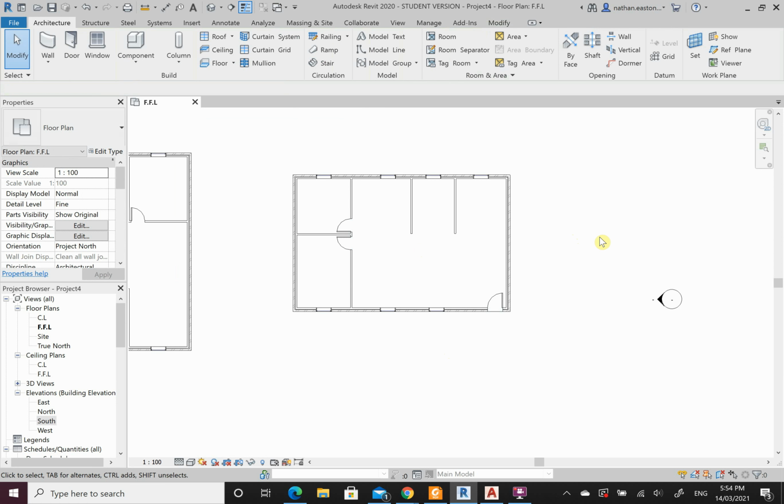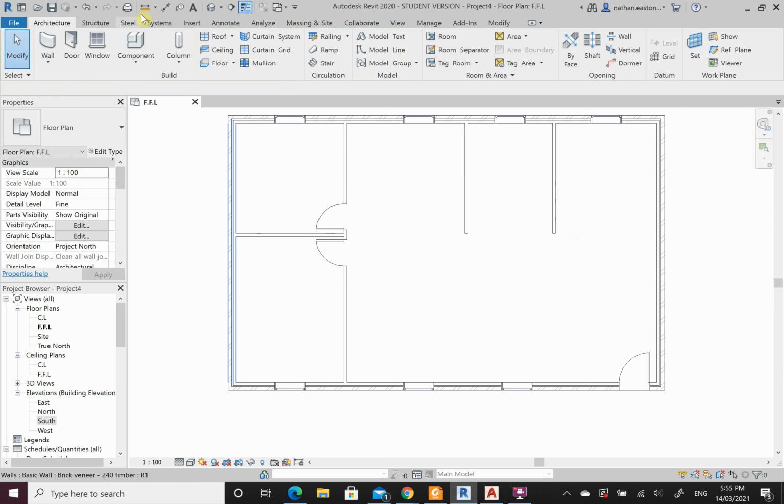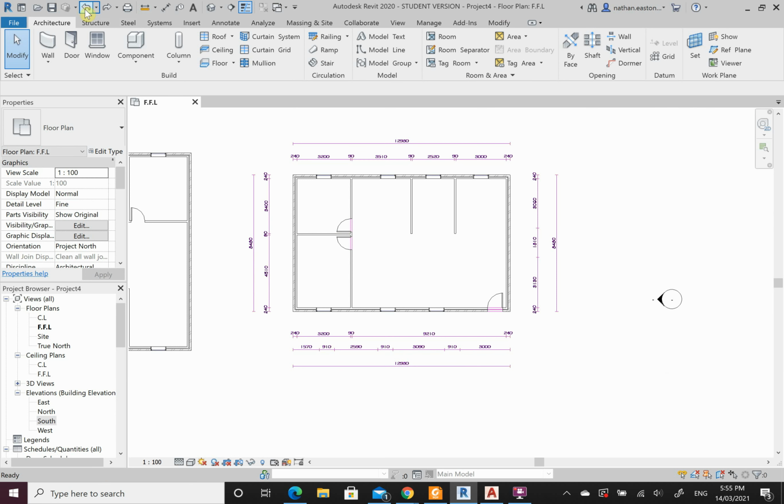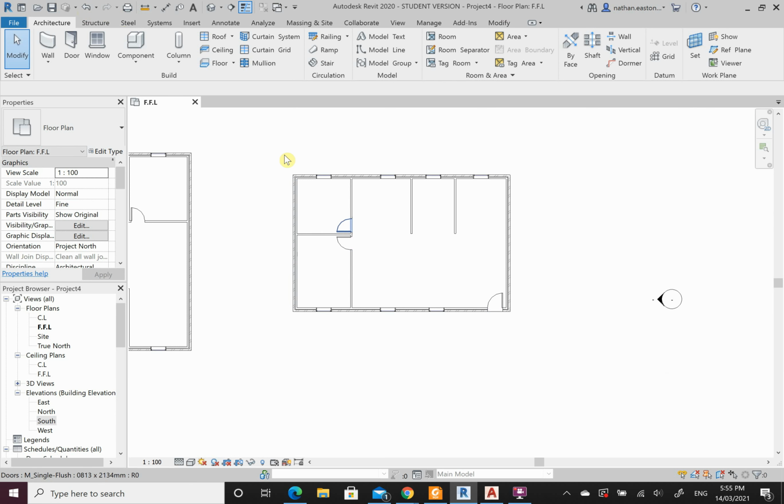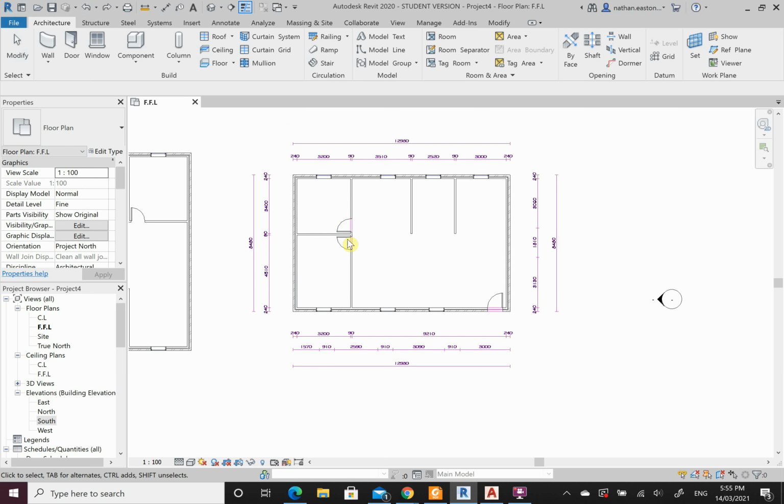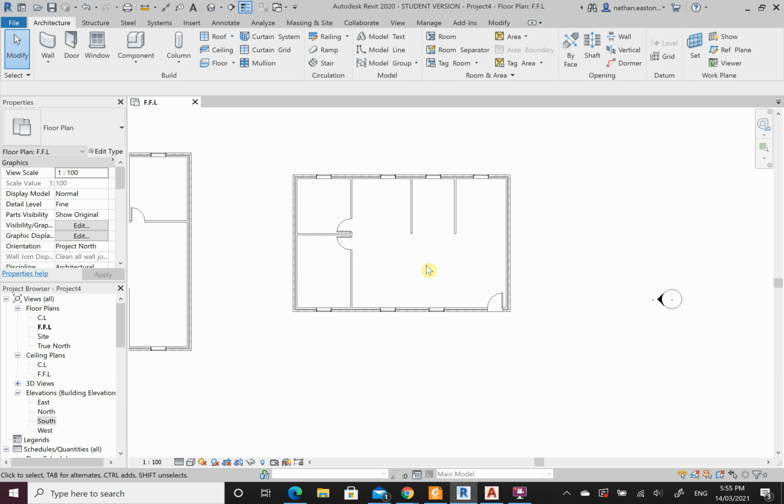Now you know the exact placement of your doors and windows from that CAD file. Internal ones, not to worry too much about. Obviously on my drawing I haven't got any internal doors showing. If you do, they will appear in Revit, so you can just click over the top of it. So I delete that CAD file out.